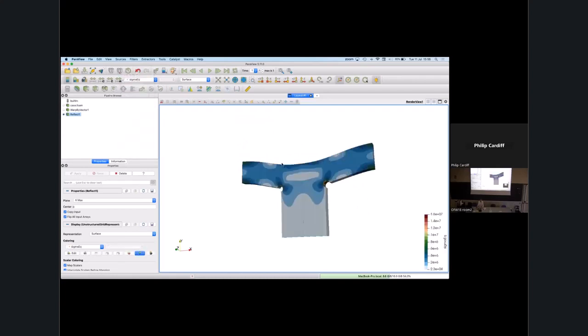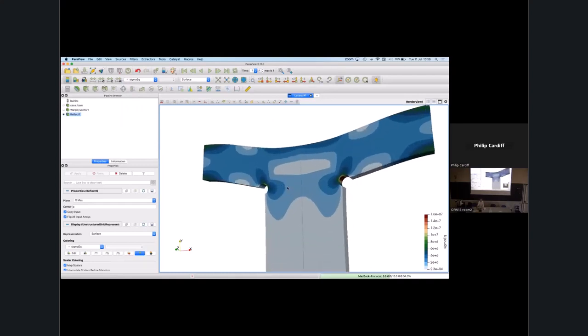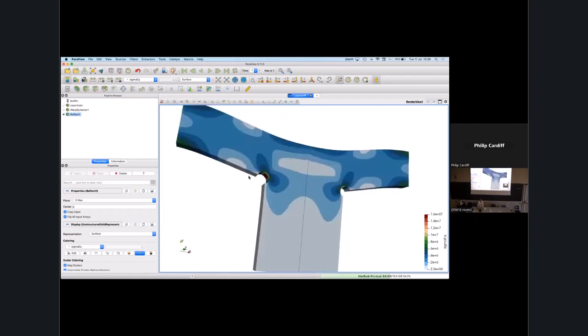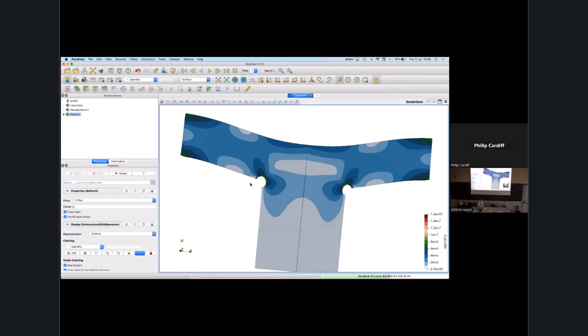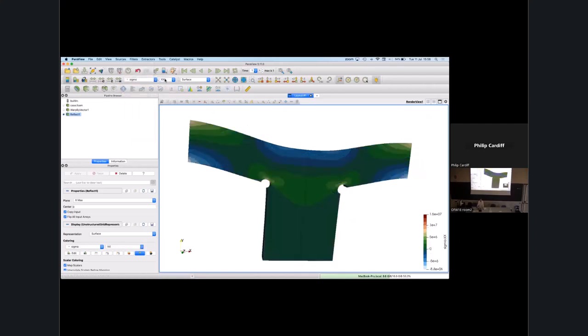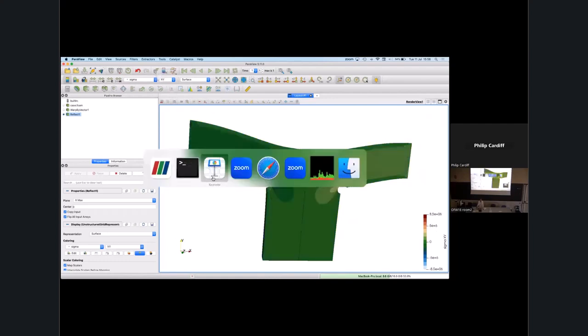You look at the von Mises stress, the equivalent stress. Normally, if you're designing a component, you want to check the von Mises or equivalent stress is below the yield stress of the material. If it's above it, then it's going to yield. In this case, it's 16 megapascals. Steels are normally in the order of hundreds of megapascals or even higher in some cases. So this will probably be fine. You can see you get a stress concentration, and it makes sense. This is maybe why you drill a big hole. If you have a very sharp corner there, then you might actually get local yielding. You can also look at all the different other components of the stress tensor, the XX, YY, etc.